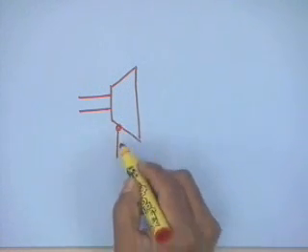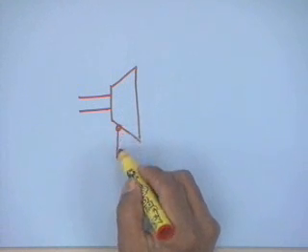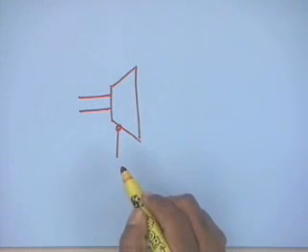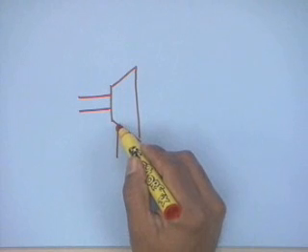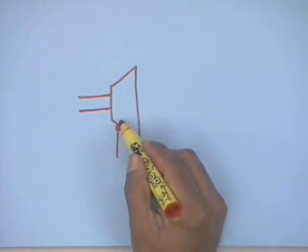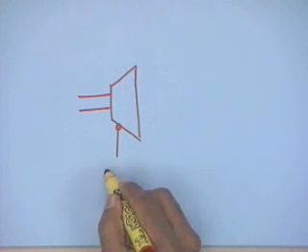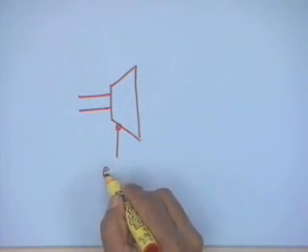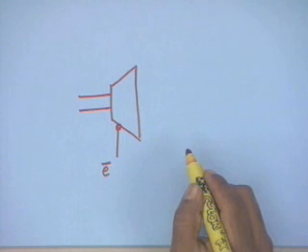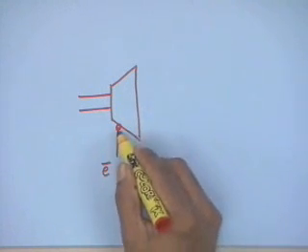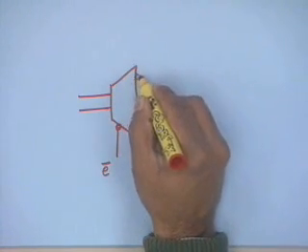That means this particular decoder is going to be activated only when this particular input is low. This essentially shows there is an inverter at the input. Of course, the inverter is actually inside the decoder. So typically we write this input as E bar or enable bar. So basically with a 0 input this will be enabled.